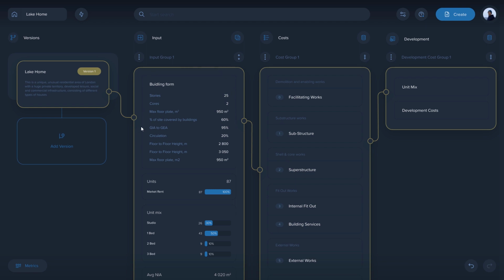After that, you have your building input and you already have the volumetric model, which is hidden right now. What you need to do is just put in your rates, because you have your own structure. It can be an NRM structure or your customized structure or customized NRM or whatever you have. You just need to connect your own cost rates benchmarking system. And after that, we will connect all quantities and areas which we extract from this step with your benchmarking system.